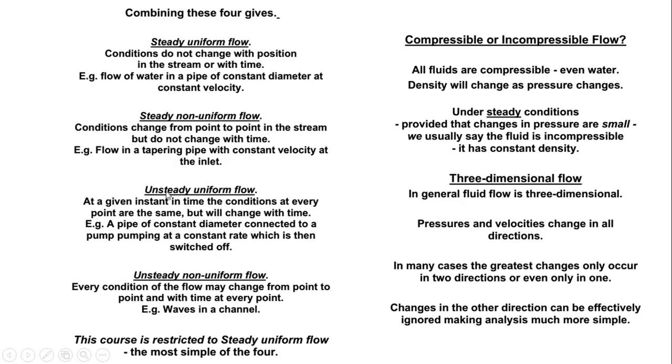Unsteady changes with time, but uniform, the conditions are the same at every point. So when you combine all these flow characteristics, make sure you understand what you are dealing with. Steadiness has to do with time. Uniformity has to do with every point, the position that you are looking at.